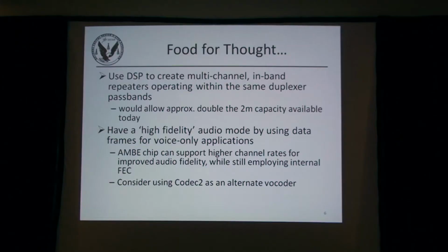One other thought, and this is tying in with the presentation on Codec 2. It's interesting, some people like or are used to the audio in D-Star. A lot of work, David was talking about with Codec 2, shows how difficult it is to compress audio and keep the fidelity as you go to lower and lower bit rates. D-Star took that plunge, went down that path, went for the gold, if you will, to minimize the bandwidth. But some people really do not like the audio quality that's coming out of the AMBE chip.